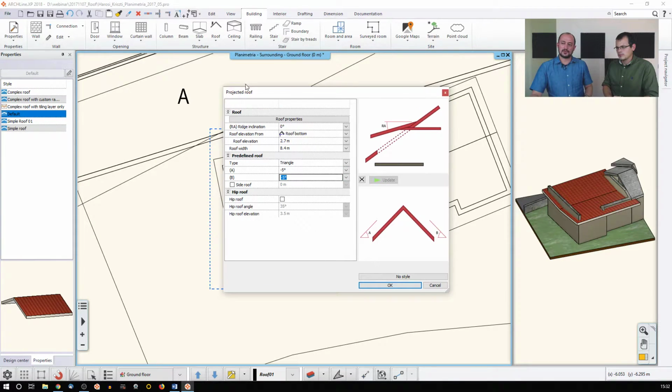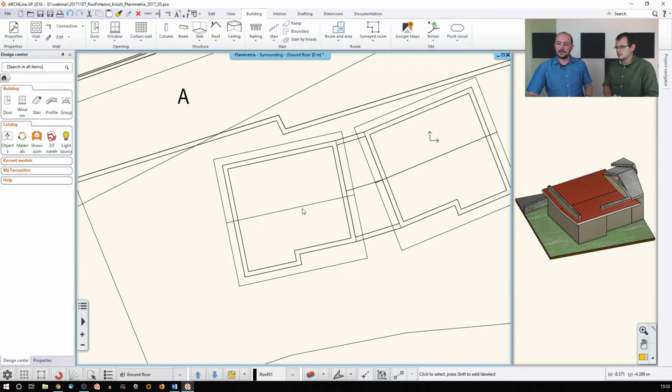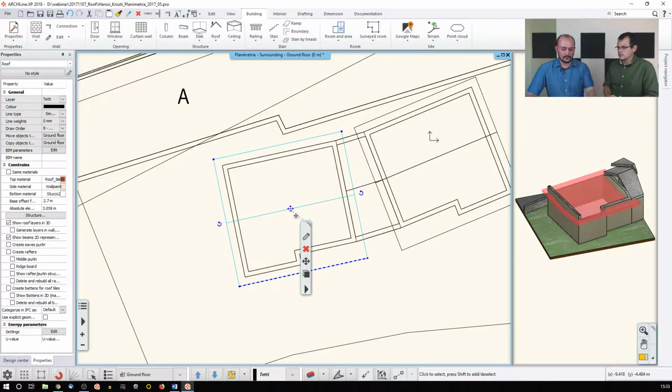Now we are talking about a projected roof, and this is where we start going in the direction of roof windows and projected dormer roofs. But the point here is that there are specific roof shapes that you can simply draft and set up at different angles. You can even make it asymmetrical, like we did 2 days ago. The same way you can change it, and if it's even more complex, like one triangular shape here, another one here, another one here, you can use the tool that I'm about to show you now, and that's called the roof by 3 points, or the roof by reference line.